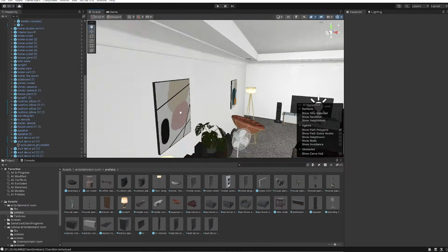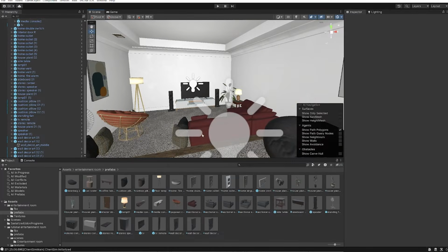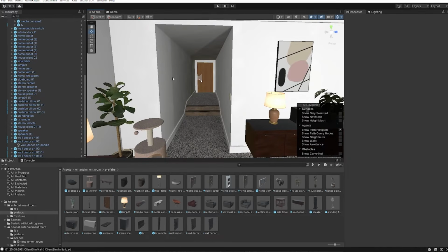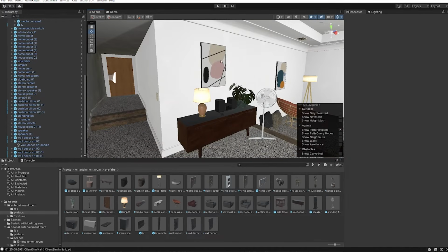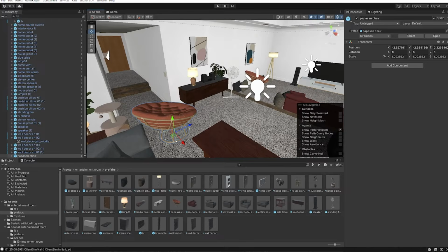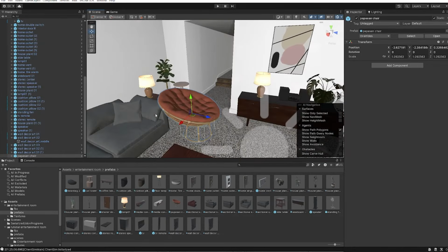I just finished decorating the space, so this is kind of what I chose to set it all up like. One thing I do want to mention that I didn't mention when talking about movement is these pivot and global options. When you bring in an object and you look where your arrows are, I think by default it's on pivot. You can change that to center, where it will choose the center of the object. Sometimes that's easier to work with than the pivot.